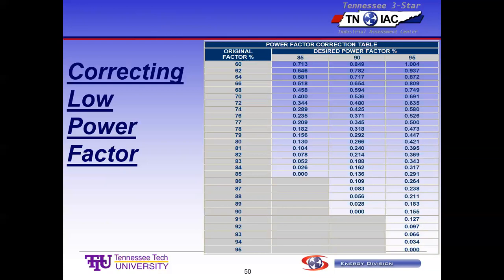So if your power factor doesn't move around, if it just sits there, then okay, you can do it with one bank. If it jumps around all the time, you're going to have to break that up into little modules and put some switching in it. And the only way you're going to know is to put a meter on and record that for a while. These days, the utility meters are getting better and better. A lot of utility companies have this data. They save like a year's data on each customer, and they can just give it to you, 15 or 30-minute interval data, and show you that.